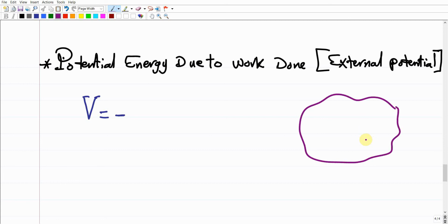We said from the beginning of this class that this object includes some particles inside the continuum, and these internal particles are already subjected to some body forces, F. This force will result in some movement, pushing the particle to move with a displacement U. If we multiply the force times the displacement, definitely this is going to give us work, or an external potential, as we're going to deal with it in the total potential energy that we're discussing here.